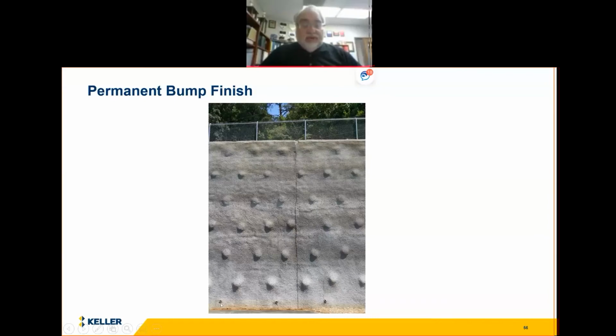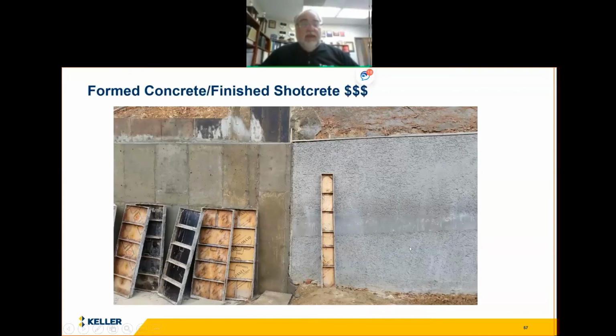And here you also see at the bottom some weep holes that are connected up to chimney drains that have been placed against the soil and shotcreted against. Very always required in soil nailing, as well as a construction joint or a tension joint that you see here in the middle.